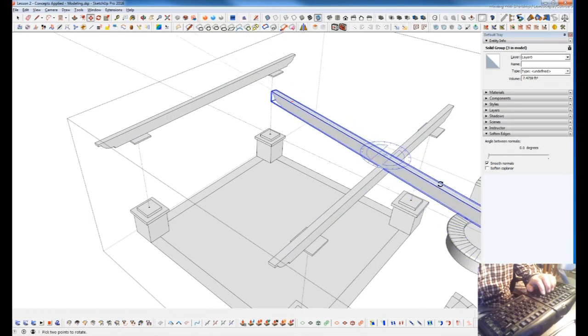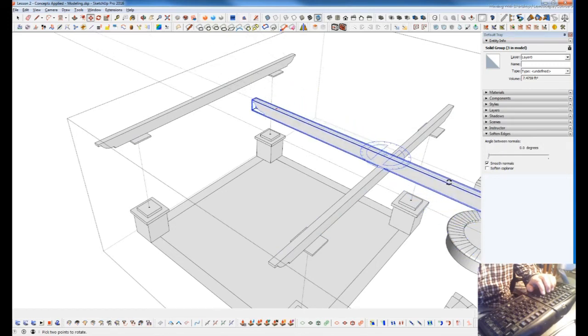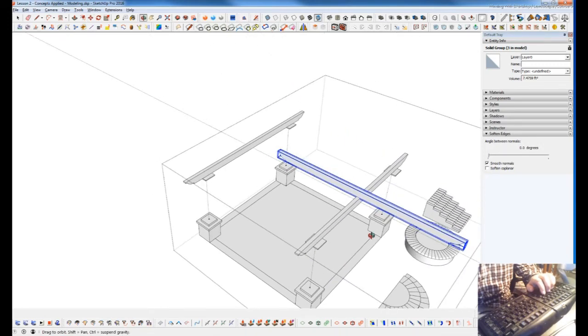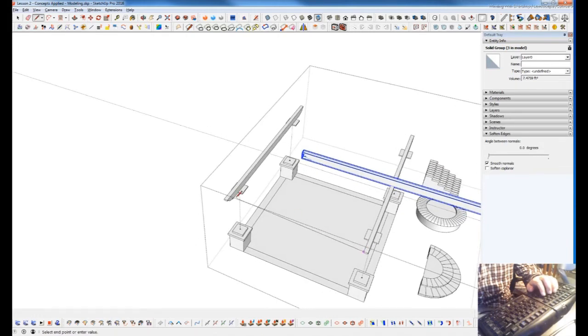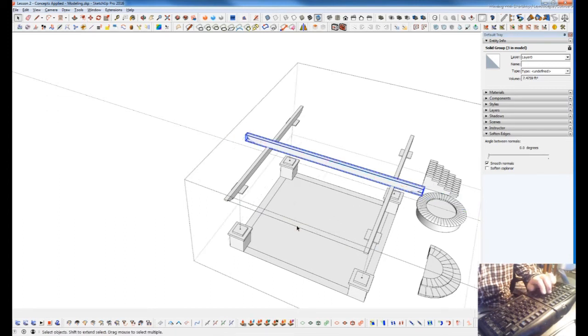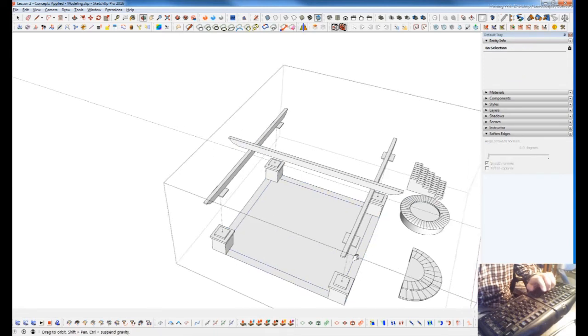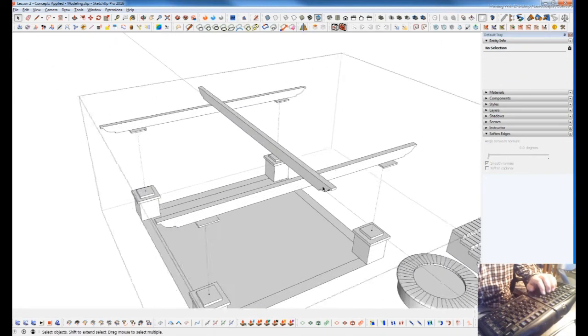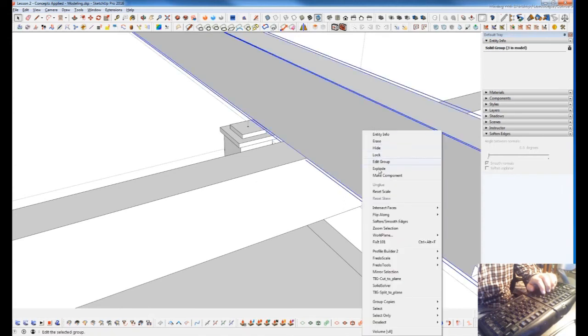Use my move tool, rotate that around to minus 90 degrees, and the reference line here, find my midpoint here, move this and snap it to the midpoint here, and then delete this. So that's in the middle.